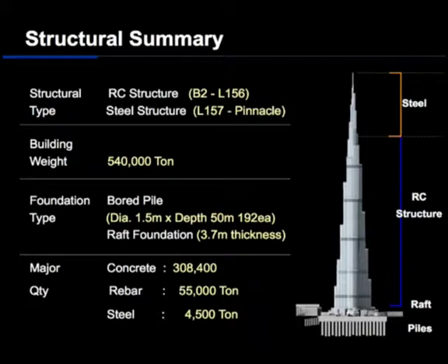Easily you can calculate that one pile must take 3,000 tons. But based on the actual on-site test result, it is more than 6,000 tons. So the safety factor is more than 2.